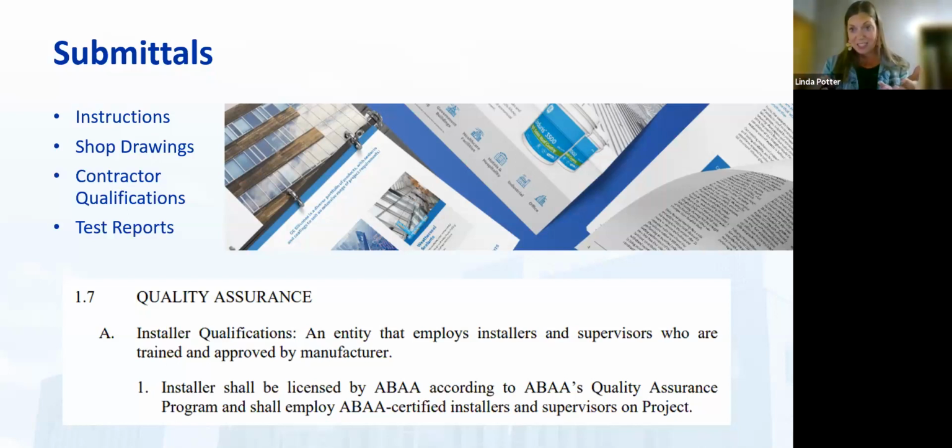What do you want? Spell it out and put it in there, because it's a completely different cost for a contractor to do shop drawings as manufacturer's standard details versus paying someone to lay out the entire building, whether they're doing that themselves or using a third party, or the manufacturer is doing it, to do some of these project-specific shop drawings. Just make sure we're clear on what we want there and the cost impact that can happen one way or the other if we're not clear about what we expect there.